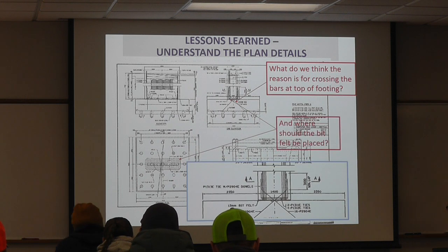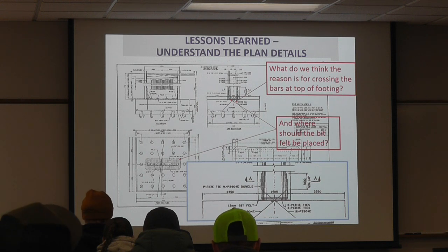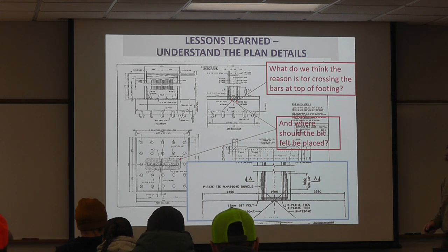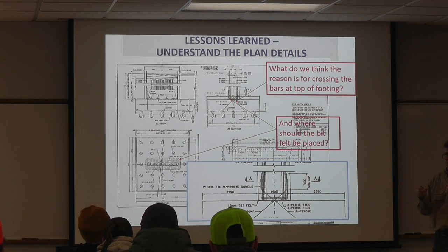And so then, where should the bit felt be placed? So this detail up here shows this all the way through, or so it appears. So I get out to the site just for a site visit. They didn't call me out. And I see bit felt everywhere under here except where the actual rebars were.